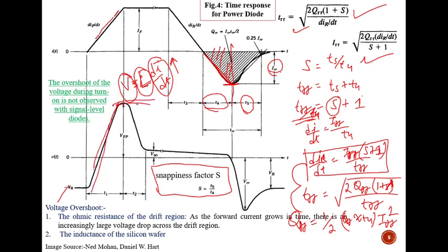Because this di/dt is very high, the voltage involved in this amplitude will be high. Always be careful about it. So that is the reason the snubber for the diode is necessary. I'm not explaining more detail on the diode characteristic, because this is a very obvious thing. Why on voltage is here, why this reverse recovery charge is here. My intention is to show the snappiness factor of that diode, and the overshoot is here, and the third one is the reverse recovery charge.